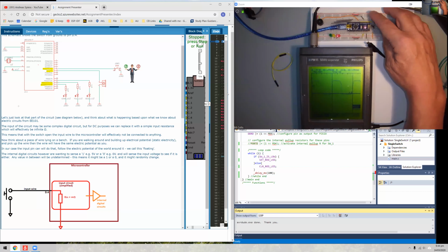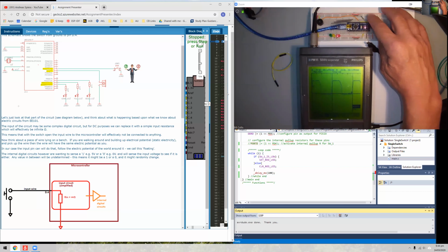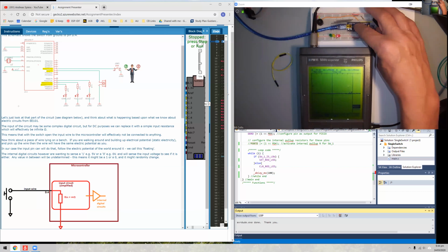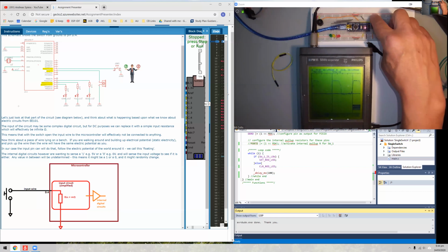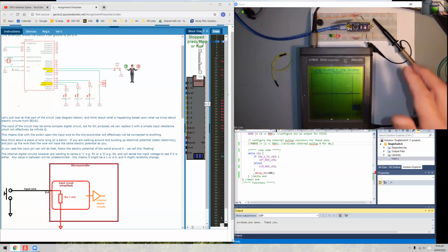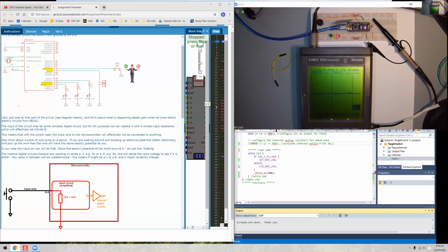When I come over here, I turn on, I do strange things to my circuit. I'm going to reset it. See if my LED won't even go off at all. It's just picking up lots of stray energy. Oh, there it goes. When I put my finger on it, it's going off. So there's some strange things going on because it's floating.